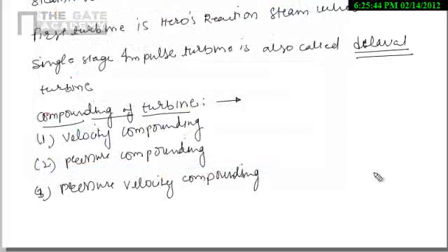We have a high rotation, but our requirement is less rotation, so we provide a gear arrangement. So we are wasting some amount of kinetic energy by the gearing arrangement. That's why we go for compounding. Whatever kinetic energy or enthalpy is required in each step we use, and the remaining enthalpy we use in the later stage, so that this way we can utilize the full enthalpy or full kinetic energy of the steam for producing electricity.